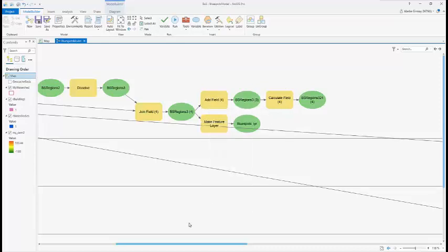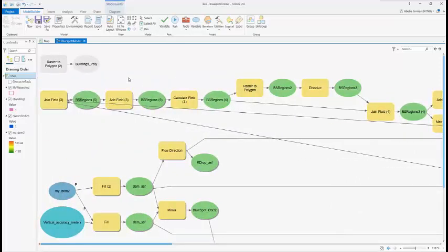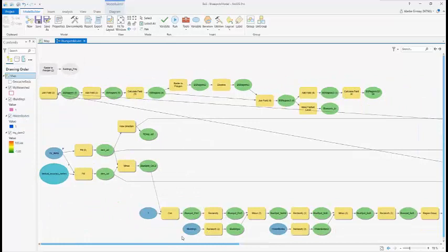But before this, according to the PDF text, there is one step that is outside of here, one tool that we will do, which is the converting of the raster to polygon. Because if you remember, at the beginning we had two rasters, one is for the building and the other one is for the water bodies. The water bodies we already used somewhere. The buildings we used here as well, and we will also use the water bodies here.